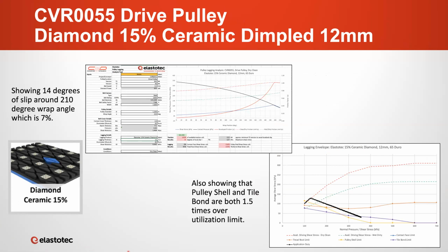You can also see here that the fatigue life of the pulley shell lagging interface and the tile bond shear stress have exceeded the limit. That means that lagging would not be expected to last the 5 years service life. Now we'll go to a 25 mil version.